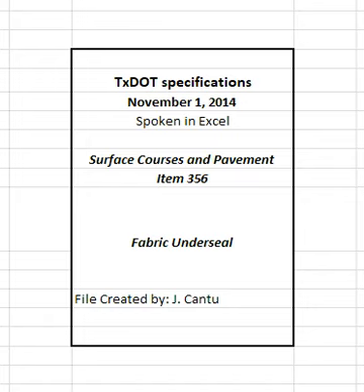4.1 Longitudinal, full width underseal. 4.1.1 Surface preparation. Prepare the surface by cleaning off dirt, dust, or other debris. Set string lines for alignment if required. Remove existing raised pavement markers in accordance with the plans. Remove vegetation and blade pavement edges when shown on the plans.